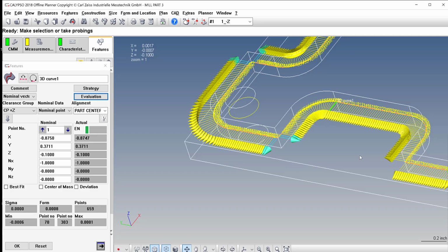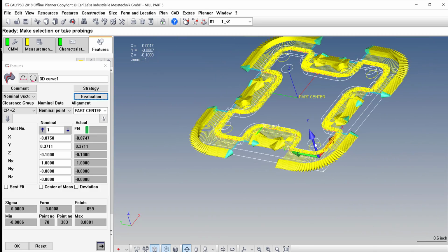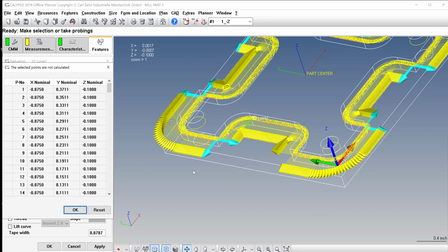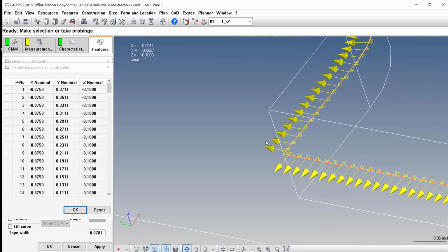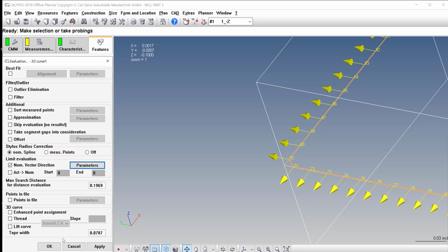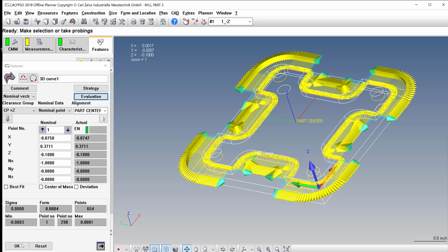So you'll notice now that the corners are blue. We do need to go back and make sure I get that one. I probably did not hold control, so I'll fix that quick. But notice they're blue, they're out of the evaluation. So go back to evaluation, get into these parameters, and then we are looking for holding control, 69 through 72 roughly. I hit OK. So now all the corners are blue and they're out of the evaluation.